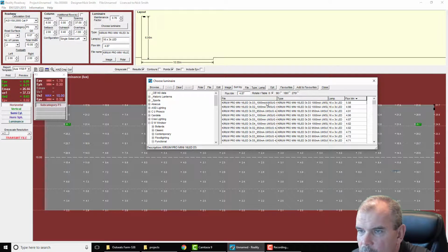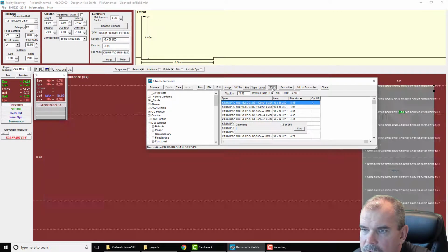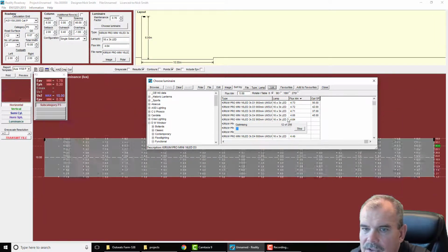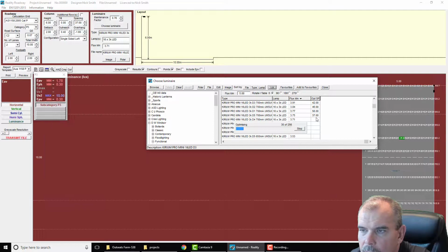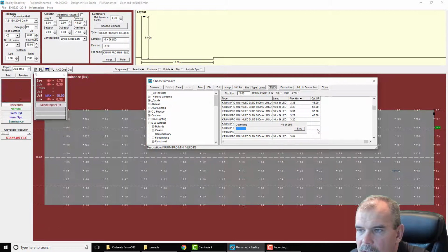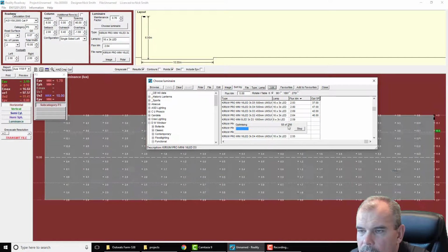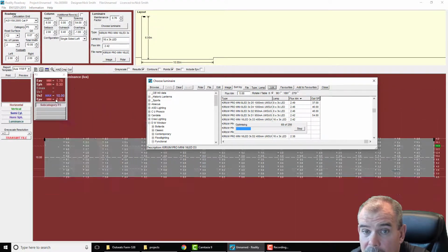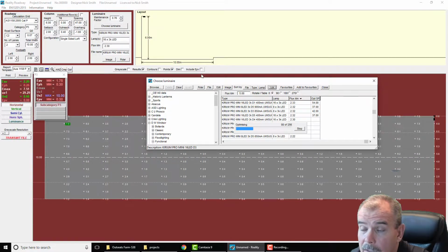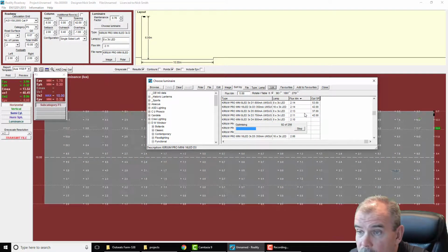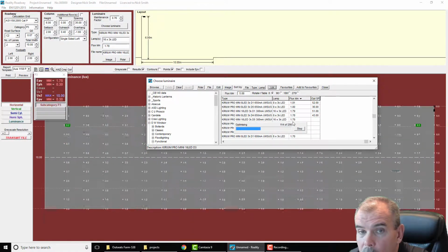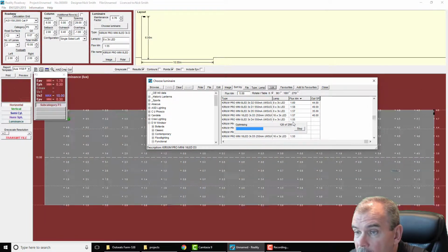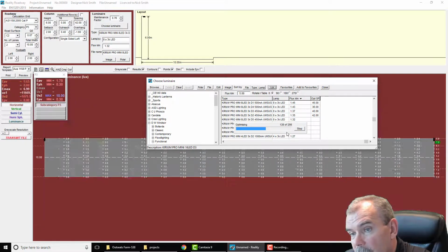The alternative is that we click on the file and we select this opt button at the top of the luminaire dialog box, and what that will then do is go through each of the optics that are available to us, and calculate for every single one the maximum spacing that can be achieved based on the road configuration and the target levels that we've included. In this case we've excluded the EPV. And for each of those it will calculate a solution that will work, and sooner or later it will get through all of those.